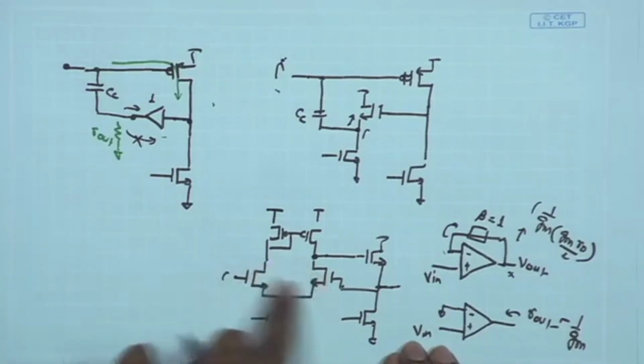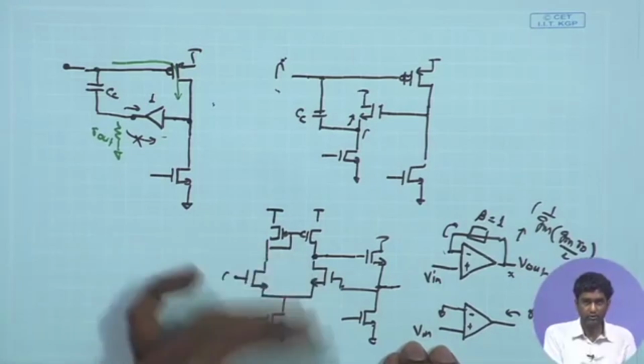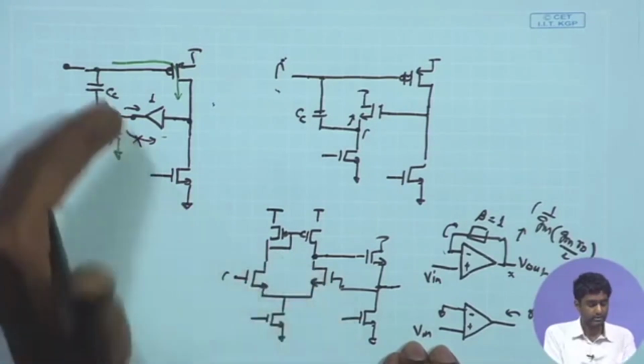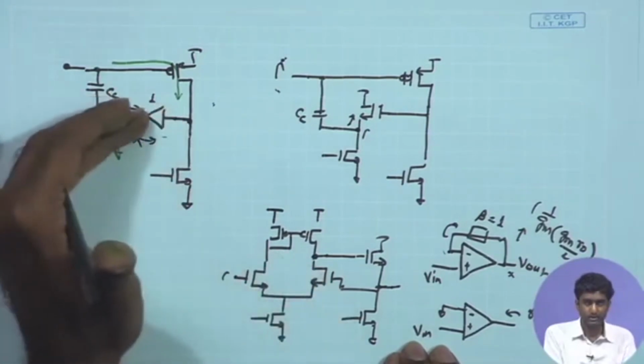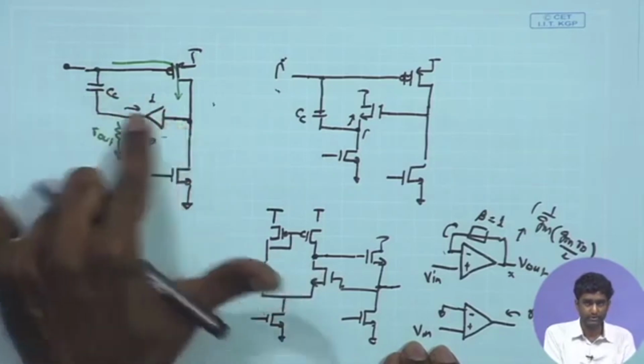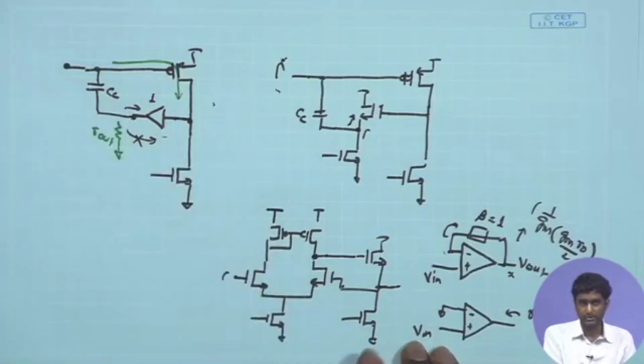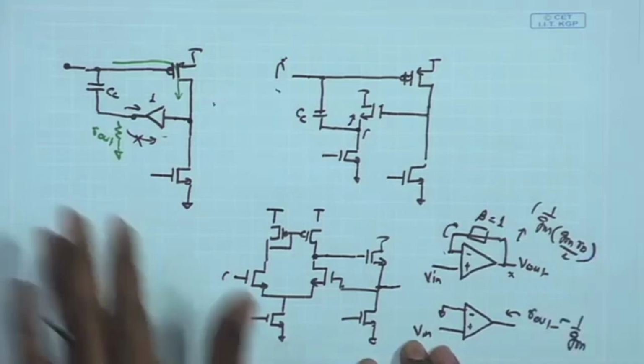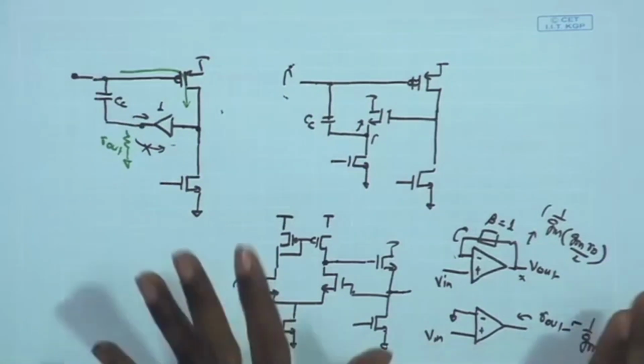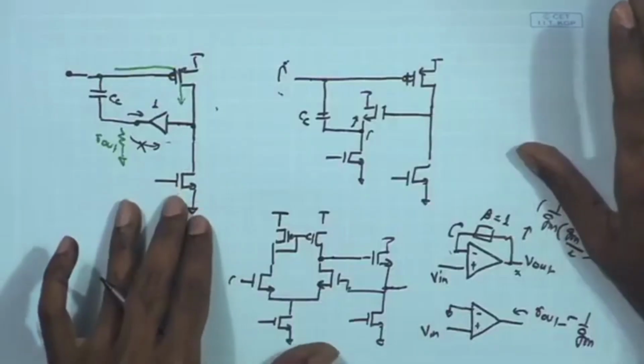We can achieve similar bandwidth at the cost of lower gain and still achieve low output impedance and a good buffer functionality for this particular unit, so that the effect of the zero is eliminated. So, this is one particular technique which we can employ in our design to arrive at the cancellation or elimination of the zero. Now, let us look at the second one.